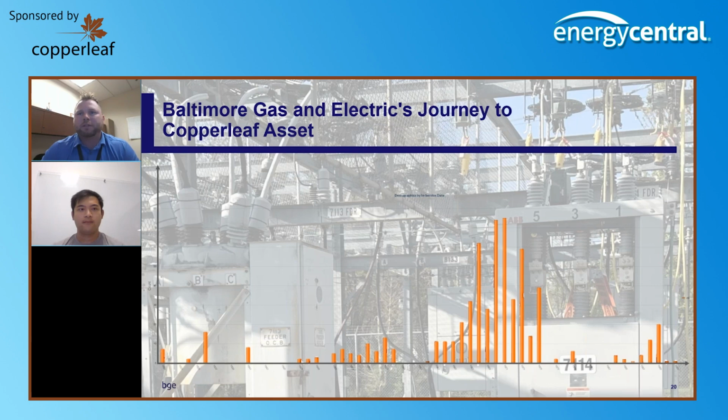So the challenge was, how do we identify which of this population of circuit breakers we can replace each year, so that we are targeting the most impactful area with the goal of eventually getting rid of all of them? We started down a path of developing an asset health score to help us better understand this problem. We worked with an internal analytics team here at Exelon to develop a model that took into account a number of different factors: CM history, age, oil sample data. We came up with health scores for all 600 some breakers.